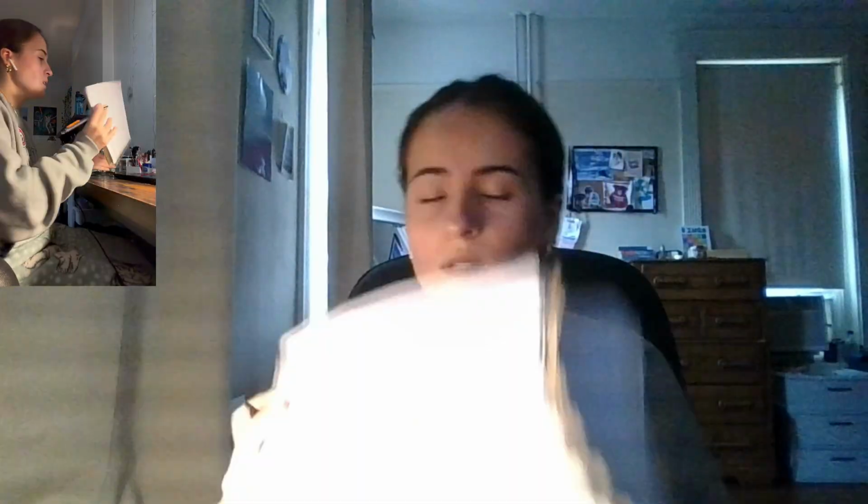And then I'm going to go ahead and pull out, we'll have negative k, and then that'll be times 1 over r, which is coming from the dT over r d theta term. I'm just moving that r to be closer to our k, because that's where the r is in the other terms. So negative k, 1 over r, dr, dz, times dT over d theta times d theta. So these are all of our net heat flow terms.